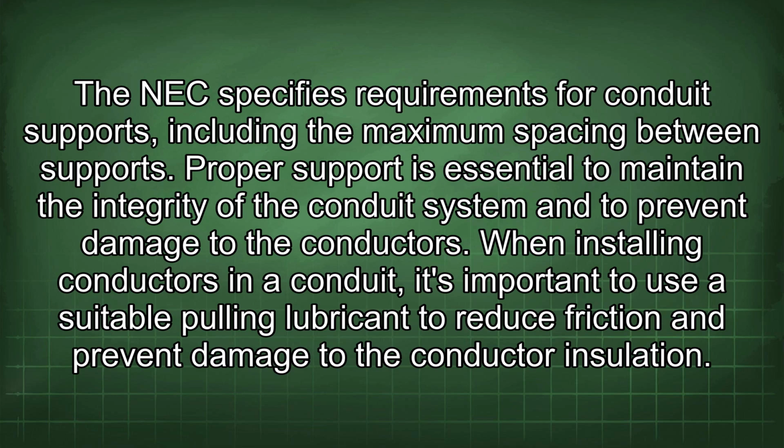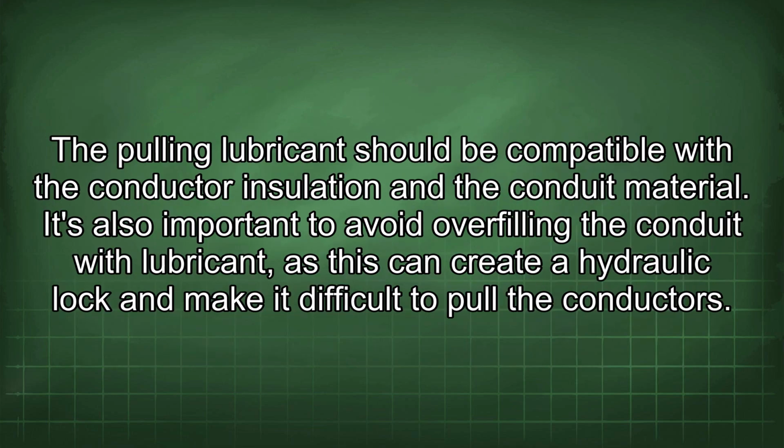When installing conductors in a conduit, it's important to use a suitable pulling lubricant to reduce friction and prevent damage to the conductor insulation. The pulling lubricant should be compatible with the conductor insulation and the conduit material. It's also important to avoid overfilling the conduit with lubricant, as this can create a hydraulic lock and make it difficult to pull the conductors.